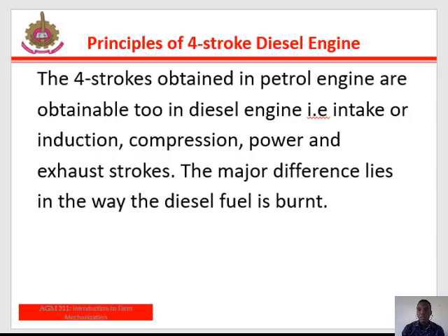Then lastly, we have the exhaust stroke. In the exhaust stroke, the piston moves upward to push out the product of combustion through the exhaust valve that is now open. The inlet valve remains closed during the exhaust stroke.